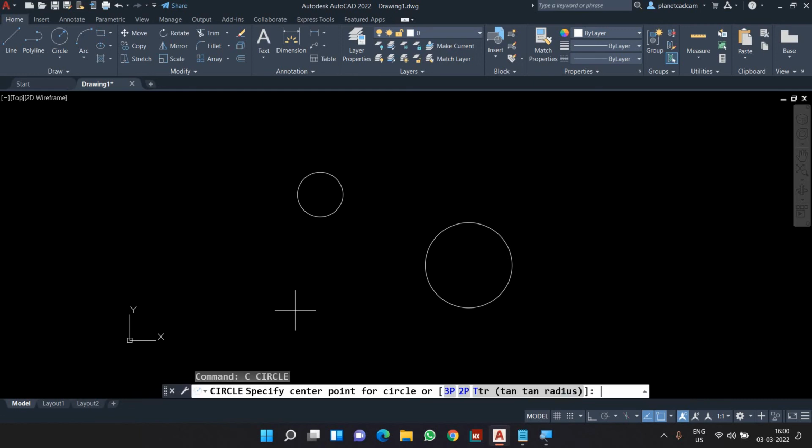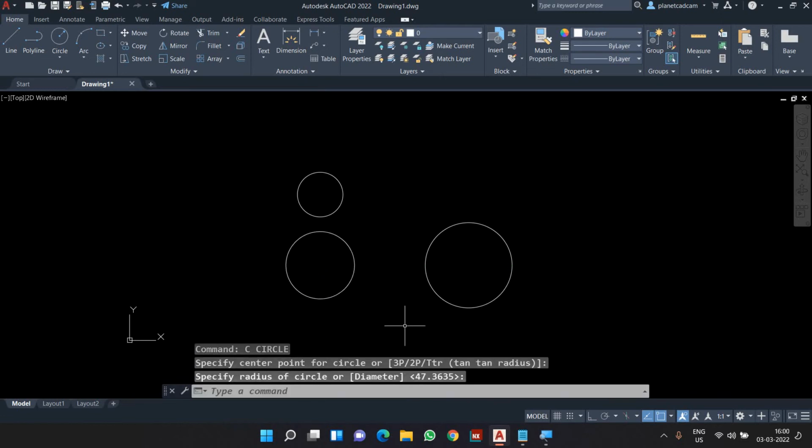So what I'll do, I'll go directly into circle. I'll highlight the first center point and move my mouse down. You can see I'm getting a temporary tracking line. I'll do the same thing to the other center point and move the mouse left. So I have not clicked on the center points, I've just highlighted them. And when I meet the center points here, you can see it is giving me a proper highlighting where these two center points are going to meet. And then I can make a circle there. So I can do the same thing just by using the tracking function.